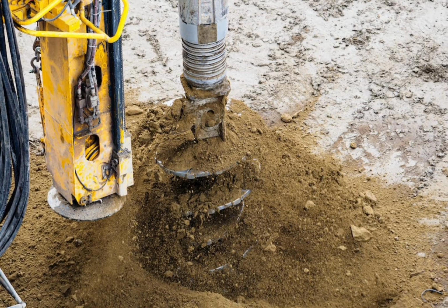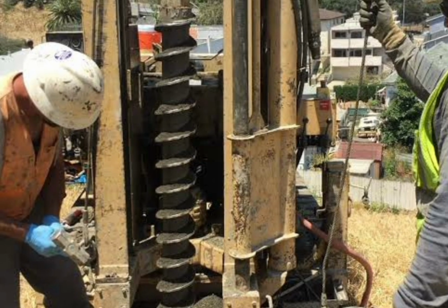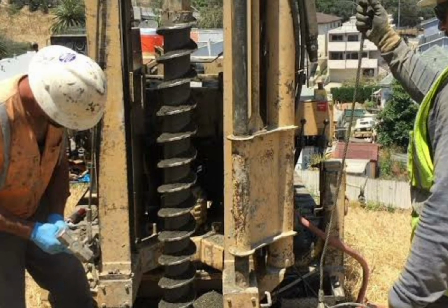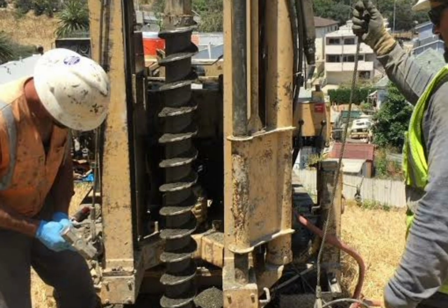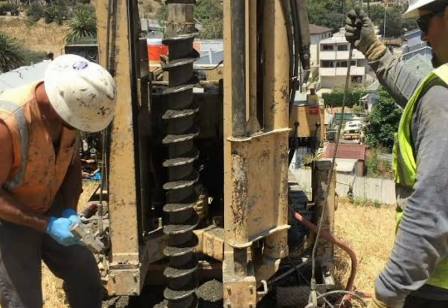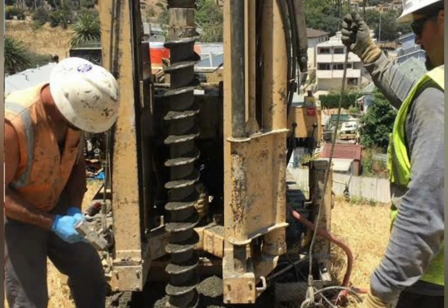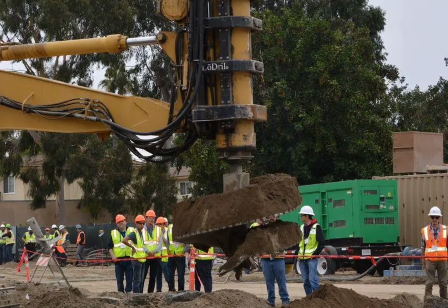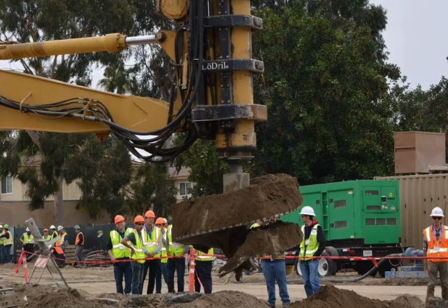Shear strength is what allows a soil to resist sliding along internal surfaces. In this test, a soil sample is placed in a box split into 2 halves. A normal load is applied vertically, and then the top half of the box is pushed horizontally, shearing the sample along the predetermined plane. We measure the shear force required to cause failure.